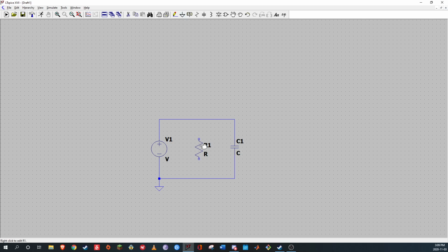But now, see the way my resistor is, if I was going to try to attach this to my circuit, now it's in parallel with my capacitor, so I don't want that. I want it to be in series. So you'll select your move button, pick that up, and hit Control R to rotate it. Now you can just snap it in here like that, and it'll automatically delete those traces. Or you could have, instead of doing that, just taken the section of the traces out right away. But that's unnecessary, because it'll do that for you.